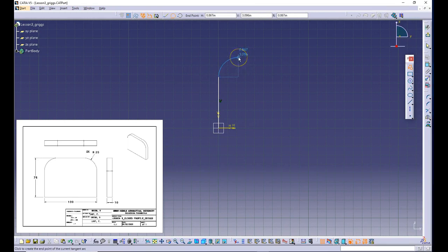edge there. And then I'm going to continue on with my line going forward, locking in that tangent relationship if I can. Click, drag away, and release to form that 3-point arc, locking in my 90-degree angle, making sure that it's horizontal with my original line on that other side. And then drawing down to the baseline where I started.